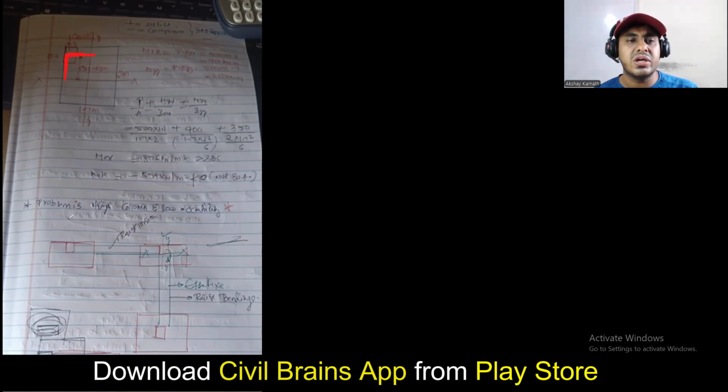So in this case your equation will become like this. That is p by a plus or minus mxx by zxx plus or minus myy by zyy. Here you have to find mxx and myy both. Here you can see, mxx is p into exx, myy is equal to p into eyy. I have done. So again, what is the load? Load is same. 500 kilonewton only is load.